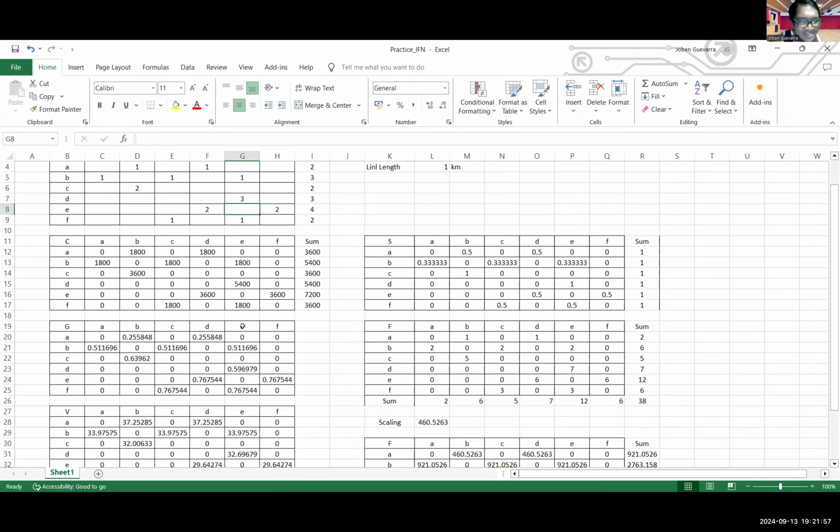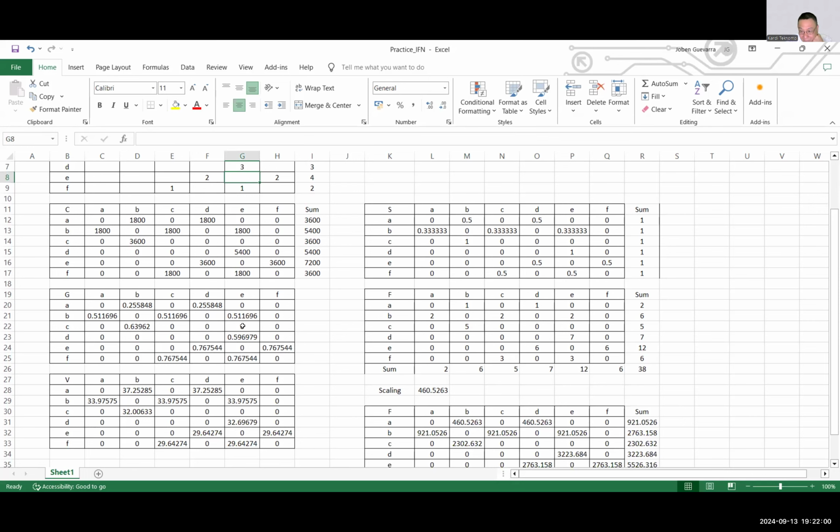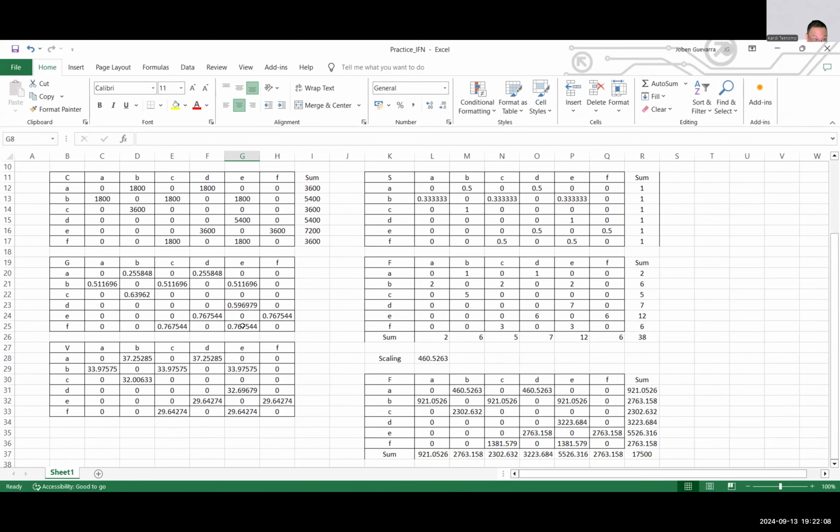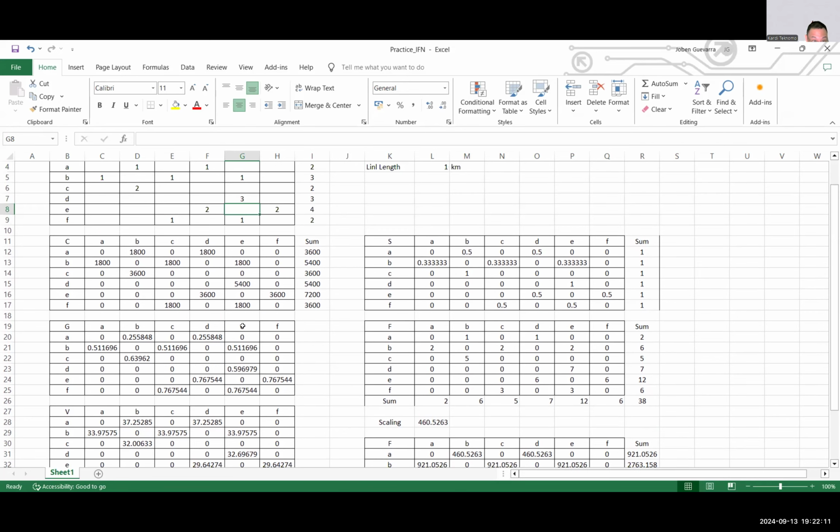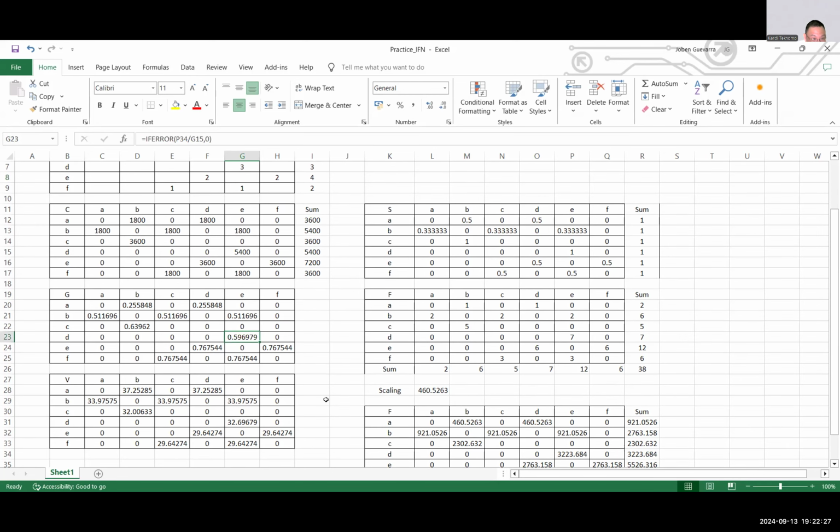Okay, then you get the alternative scenario. It all changes, sir. It changes, right? Yes, sir. Okay. So when you change that, what will happen to the congestion level? Wait, sir. I will just undo. Oh, it will reduce. A while ago was 0.9, now becomes 0.5, 0.6, and then the maximum congestion in here is 0.7. So in that case, this improvement actually improved the whole network. Yes, sir. So good.